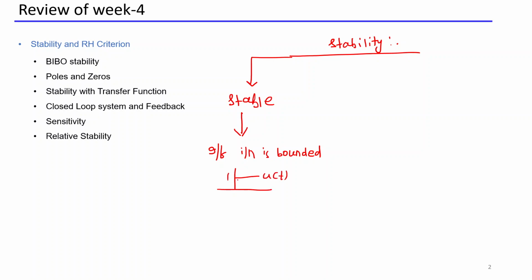It has a fixed amplitude from 1 to infinity. But a ramp signal is an unbounded signal, because its magnitude at t equal to infinity is infinity. Delta of t is also an unbounded signal. So you have to take a bounded input. If your input is bounded and the output corresponding to the input is also a bounded signal, then the system will be stable. That can be defined as the stability of the system.